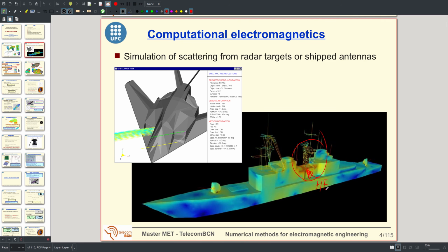So the antenna is usually smaller than the wavelength. It's a small antenna, but the whole structure of the chip behaves as an antenna. So you can see the induced current everywhere in the metallic or conducting surface of the chip, and the whole chip radiates as the antenna. Okay, and you have to analyze everything all together here.